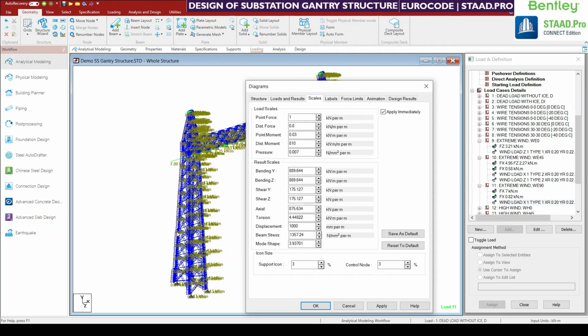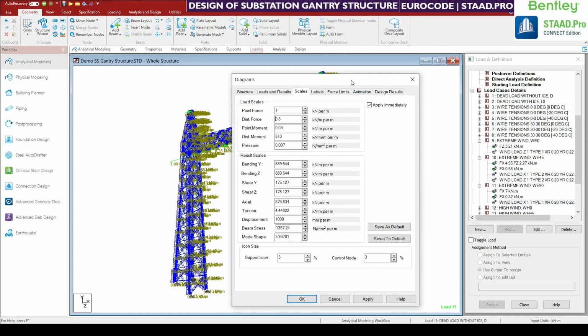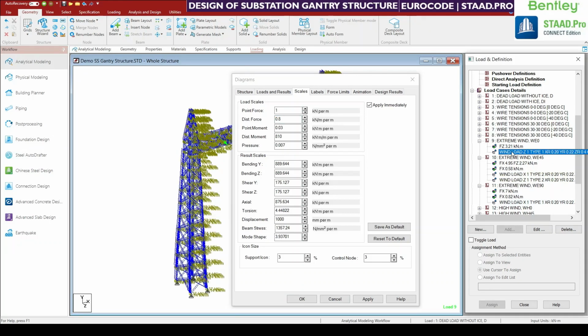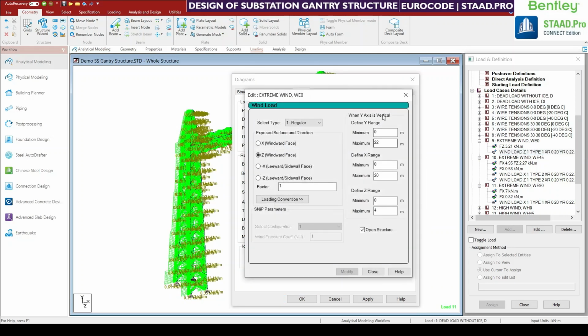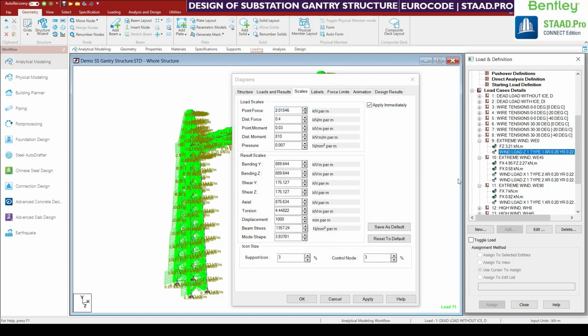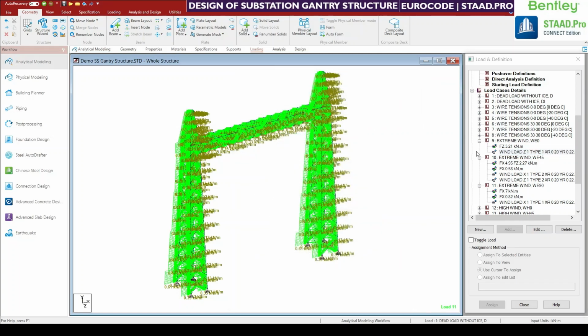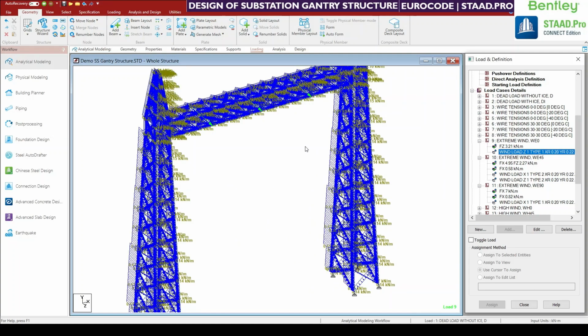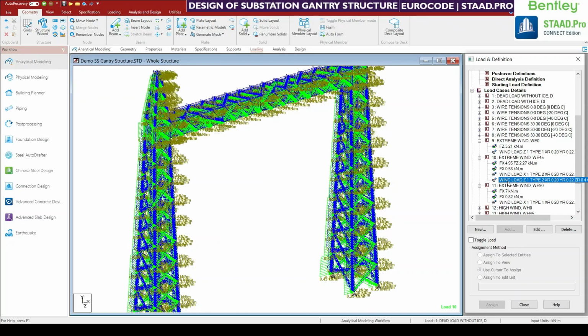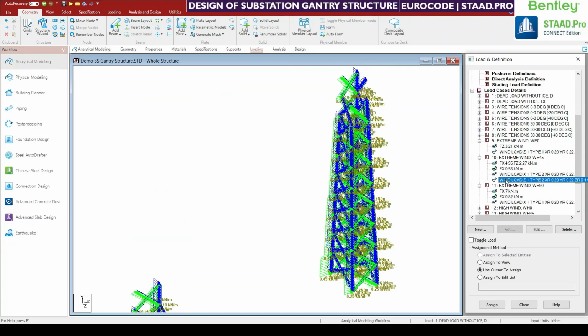It is at 90 degree, that is wind perpendicular to the conductor span. So similar like if you select load case number 9, you can see here this wind is in a direction parallel to conductor span. So in 45-degree we are having both the directional wind.